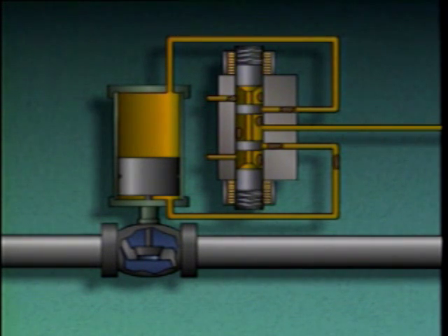Or contaminants could block the flow paths in the pilot valve. In either case, the pilot valve would not operate correctly, and the actuator would be unable to position its valve correctly. If you notice that a hydraulic actuator is operating sluggishly, it could mean that the fluid is contaminated with water or some other foreign substance.